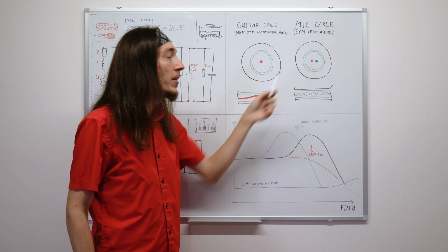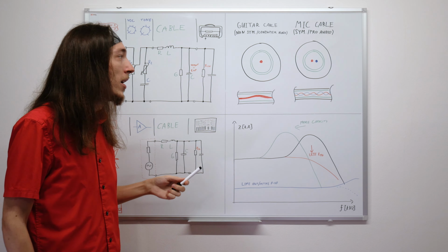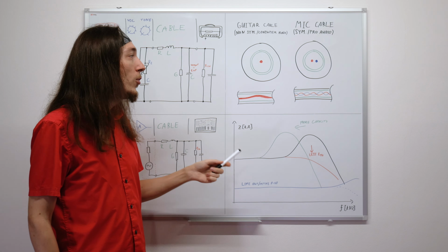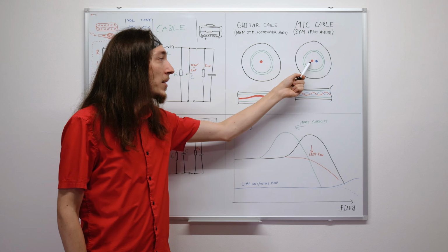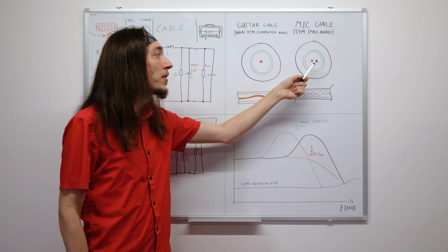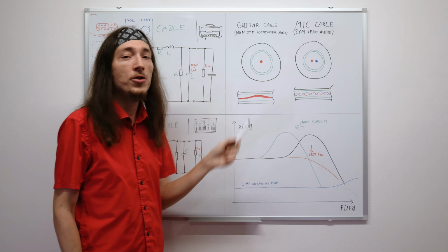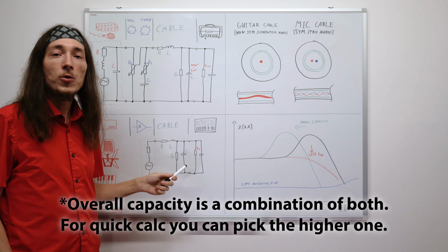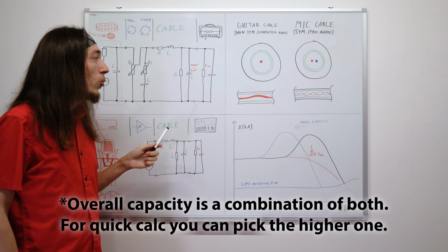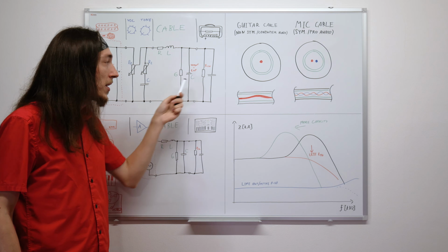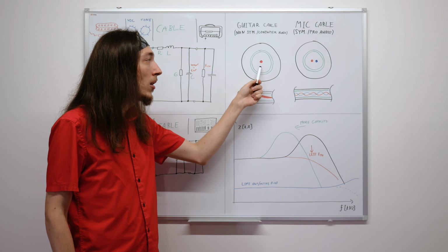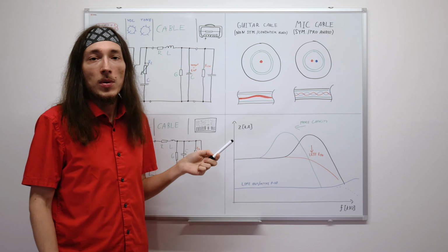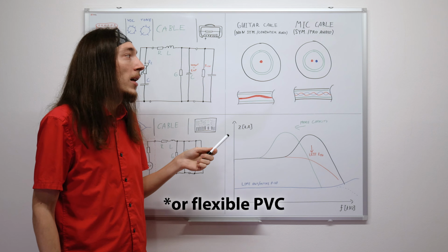Non-symmetrical cable or symmetrical cable, but in the end there is no difference if we take into account the capacity between these two wires or between the wires and the shielding. In the end we can calculate with only one value per meter. What is the most important for this capacity is the material of the insulation, which can be some form of rubber or something like that.